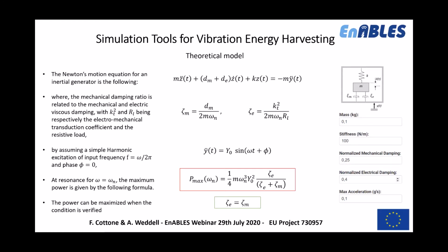It is true for an ideal vibration energy harvester, but when you design a real vibration energy harvester, you have to take into account various aspects, like the maximum displacement of the mass, the real damping that cannot be varied as you want, and also the electrical damping that is constrained by the type of transduction, if it is piezoelectric or inductive or capacitive.